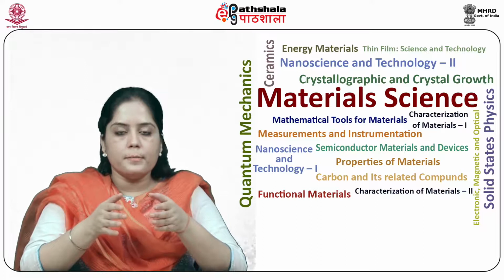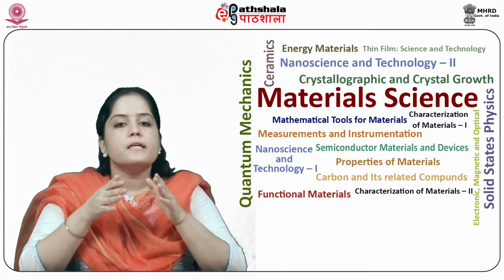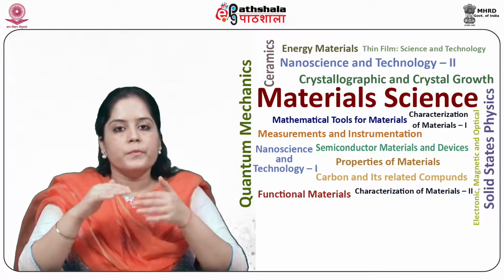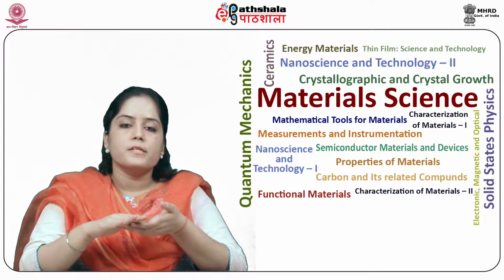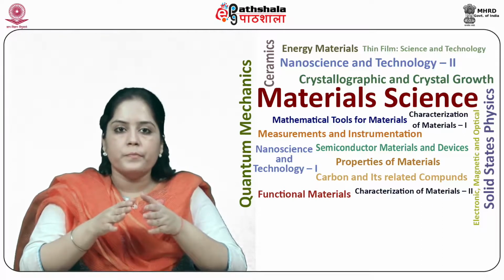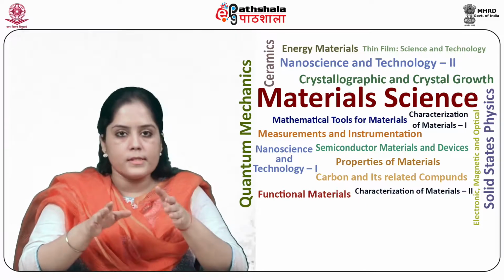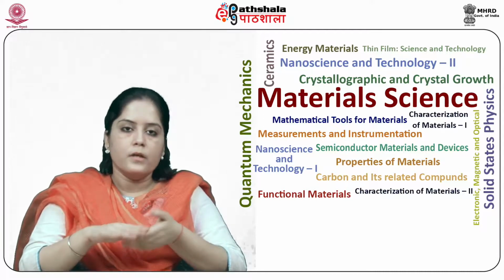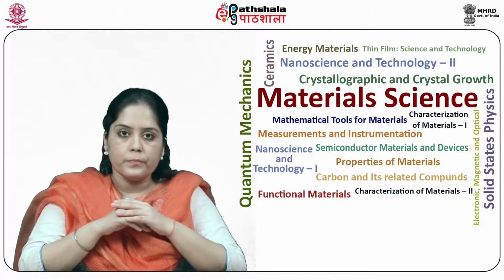Students, let us now discuss thermal oxidation. A sacrificial layer of SiO2 is needed on the surface of the silicon wafer for the selective area etching after opening of the window. The SiO2 can be grown on the surface using thermal oxidation. Therefore, oxidation of the silicon wafer is the most important process. So, a three-zone thermal oxidation process is used to grow a thick film of SiO2 over the silicon wafer. The thickness of the SiO2 thin film strongly depends on the oxidation time and temperature.